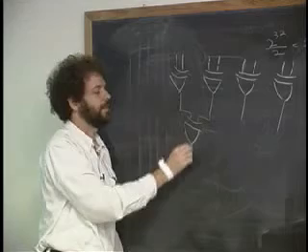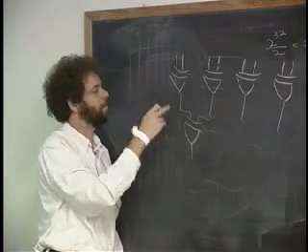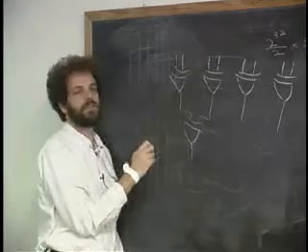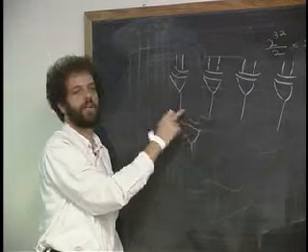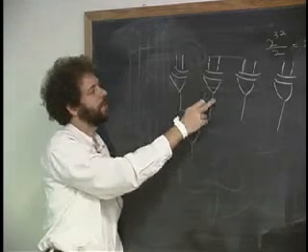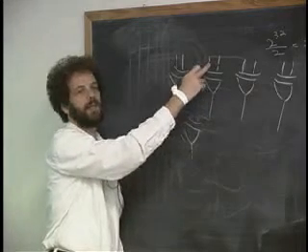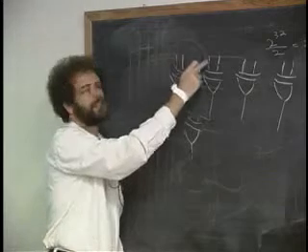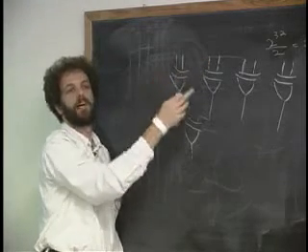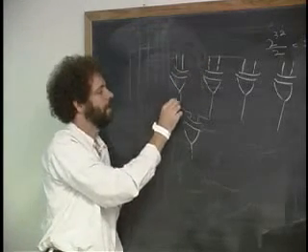Put another XOR gate. And this tells me the parity of 4 things. Because this can be 1 if one or the other of these is 1 but not both. And if one of those is 1, it means that one of these is odd but not both. Right? So either both of these are 1 or none of them. And one of these is 1, so the number is odd. And so this is saying odd.